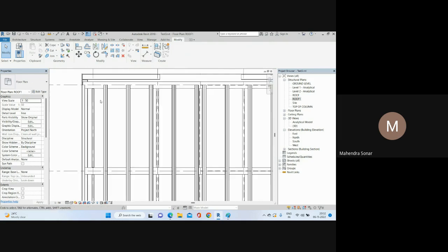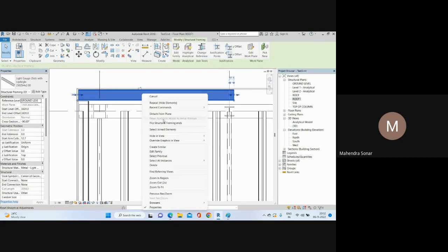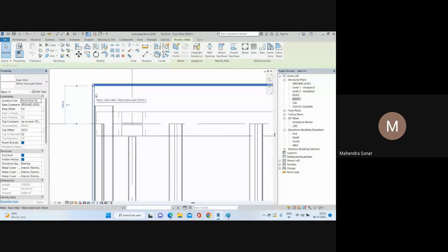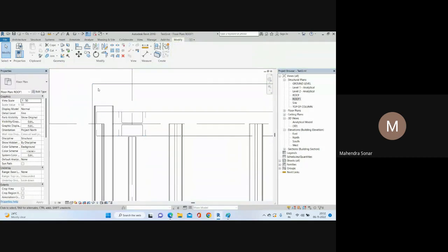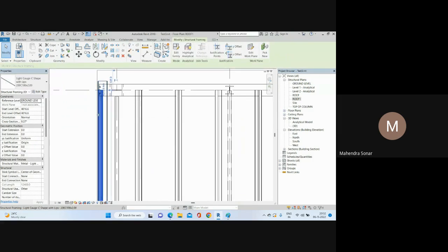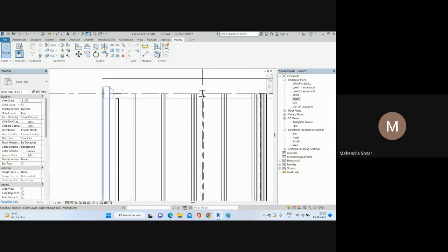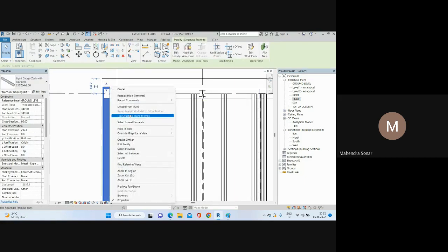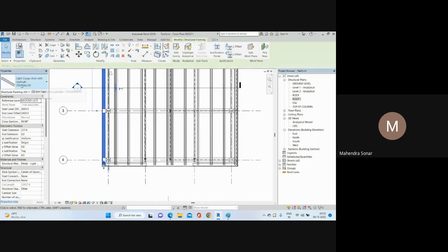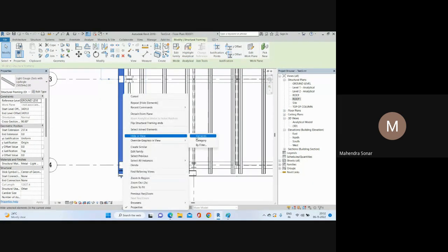Then all the purlins, okay, side guards you need to hide, because your plan looks messy. And this wall you can just also hide. We will cover this in elevation. So this is your roof line. Okay, so hide all those Z purlin side guards, only side, not your top purlins. So oops, no need to hide this. This is our end purlin. If I select, so this is C purlin. Okay, yeah, this is Z purlin, so I will hide this.